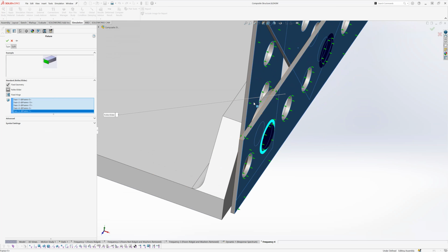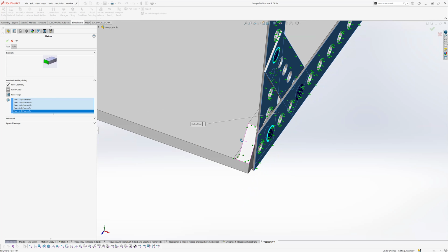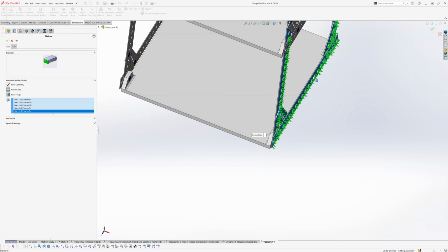And a question you might also be asking: if the washer is not able to slide in and out, and by definition these frames should not be able to slide in and out, why do I need all of these roller slider constraints? Well, just because it cannot slide in and out at this point does not mean that it cannot deflect in the middle. So this can end up looking like that, or something like this instead of going here. Just because it's prevented from moving in and out, or translating, on this specific point here does not mean that the whole frame itself cannot deflect in that direction. So that's where the roller slider comes in.